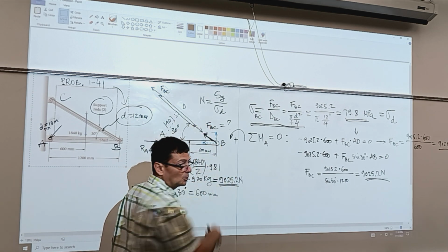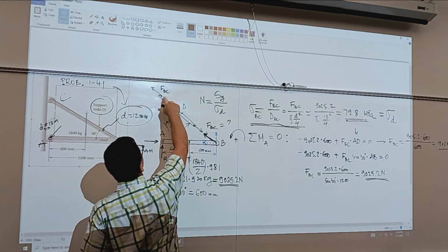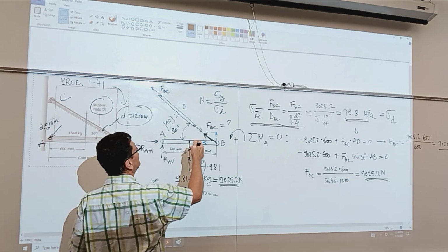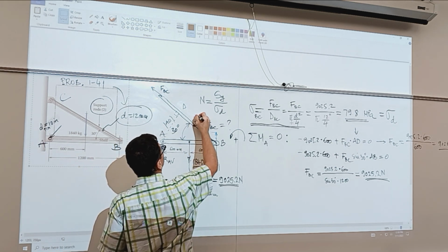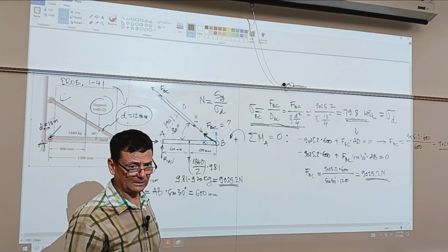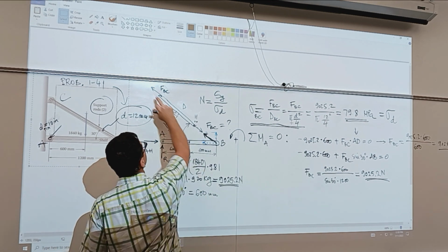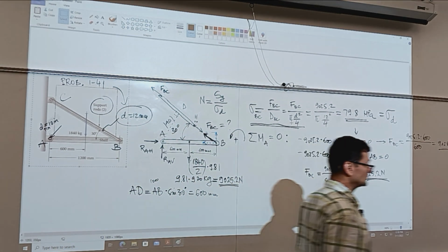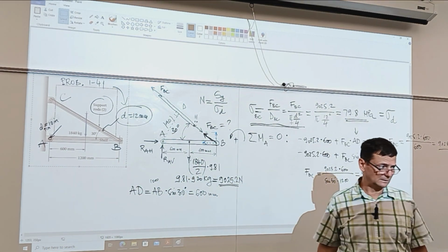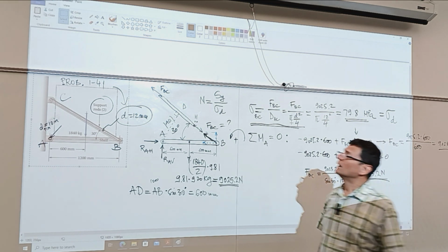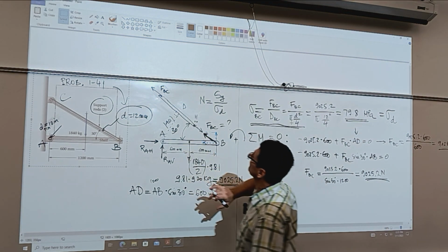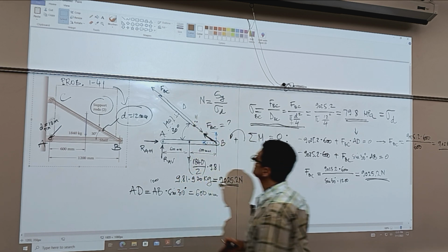Aging, you have corrosion. You need to be careful if it's corrosion. Corrosion weakens. It could be, like I say, oftentimes it's elsewhere that you focus your attention that failure occurs. The clevises at the end. So you're putting your signature on the drawing, and you're responsible if it fails elsewhere than you anticipated.